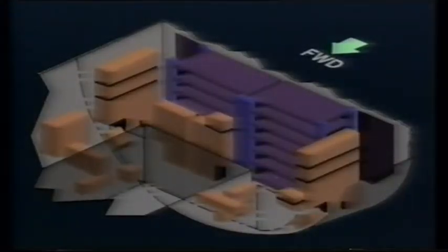In the main equipment center, on the forward left side, is the fuel system card file. This card file contains fuel system management cards, fuel jettison control cards, valve position logic cards, fuel system ICAS interface cards, and the single point sensor cards, which monitor fuel levels in the inboard main and center tanks.